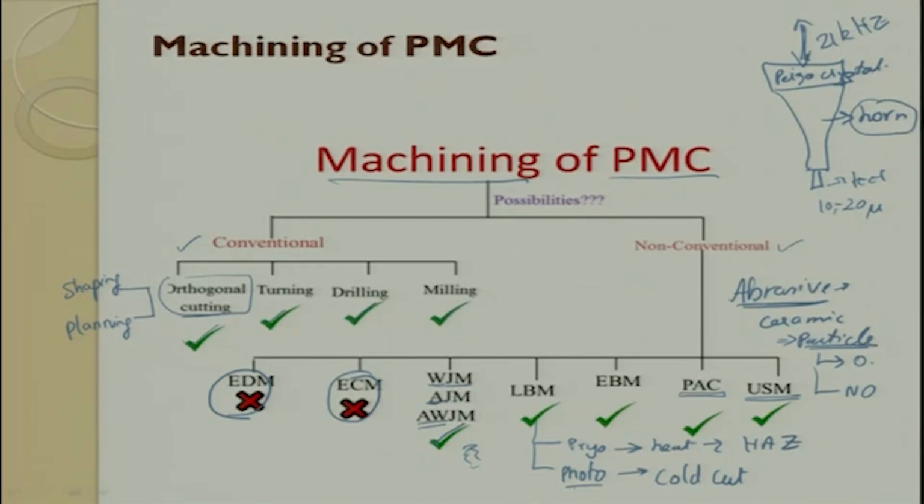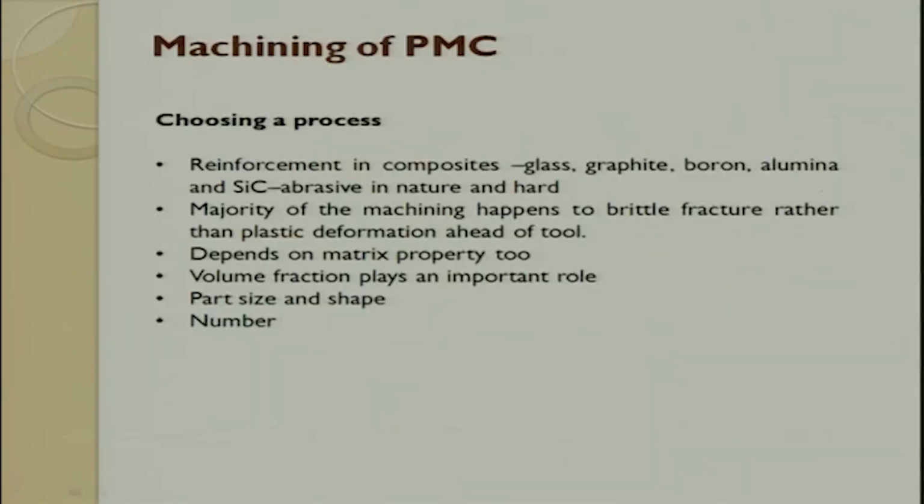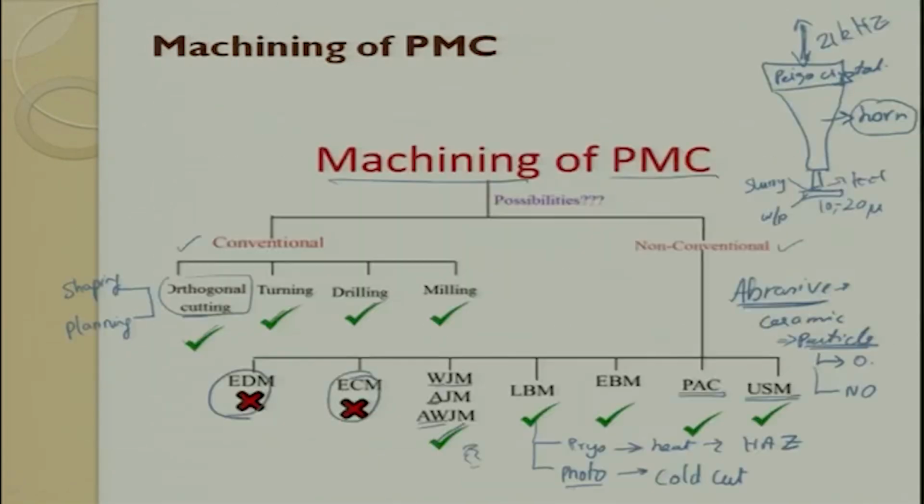So, this is used for creating high aspect ratio holes, and between the tool and the workpiece we pass abrasive slurry. So, a slurry is passed. This tries to hit the workpiece and remove the material which is there in the workpiece.